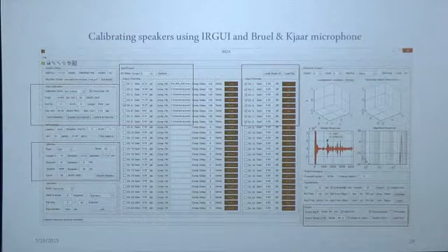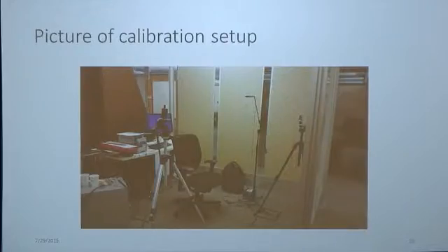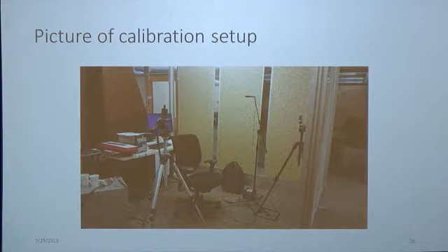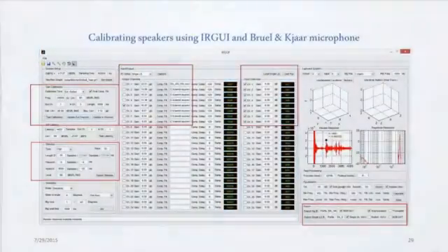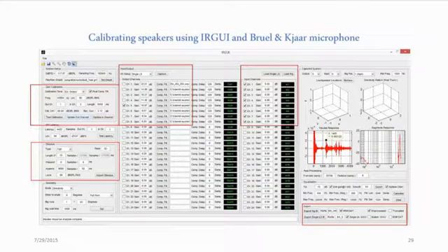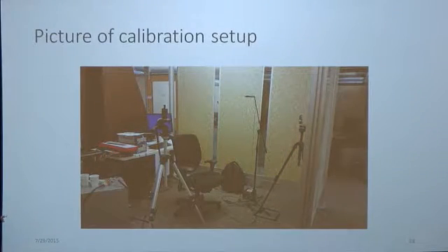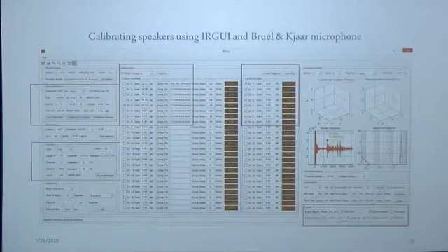So how was this actually done? To calibrate our speakers, we kept this microphone at 1 meter distance, and we pinged through all of our speakers, and the responses recorded here were basically what you saw for one channel. And to calibrate the receiver setup, we used a transducer from this setup. We again pinged, and then we measured the responses using our receivers, and we recorded the impulse responses.